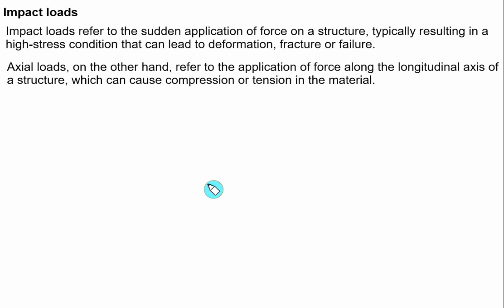Now we'll calculate the strain energy in the case of impact load, and based on the formula that we are using for strain energy, we can calculate the maximum possible stress developed. Impact loads refer to the sudden application of a force on a structure, typically resulting in a high stress condition that can lead to deformation, fracture or failure.